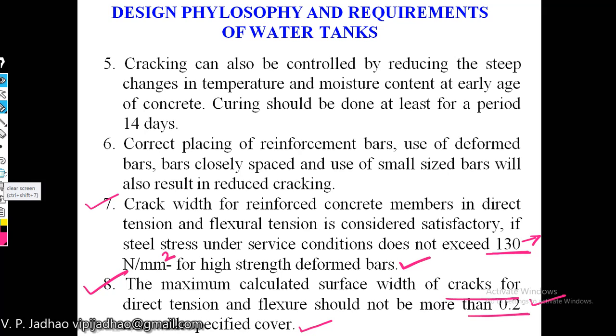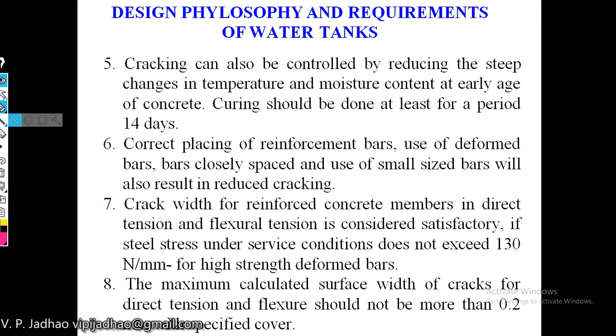So we won't be controlling directly the width of the crack. What we'll be doing is providing some permissible stresses within which the crack will not exceed 0.2 mm. So these were the design philosophy and requirements for design of water tanks.